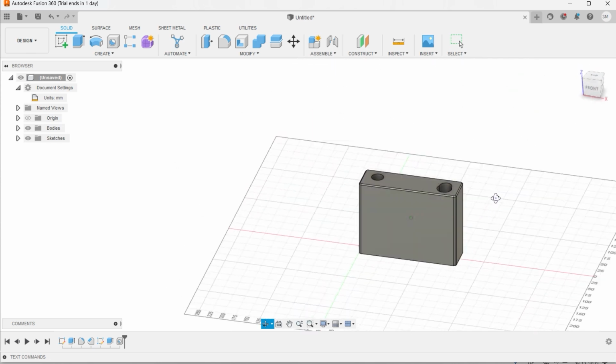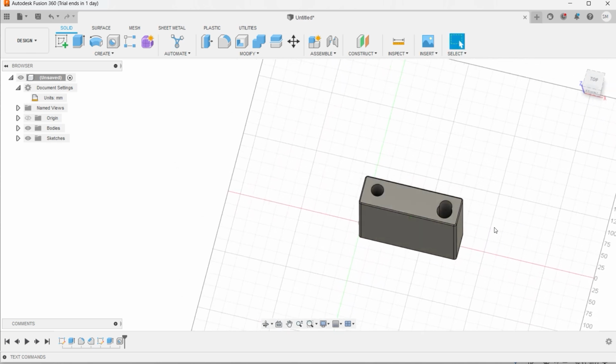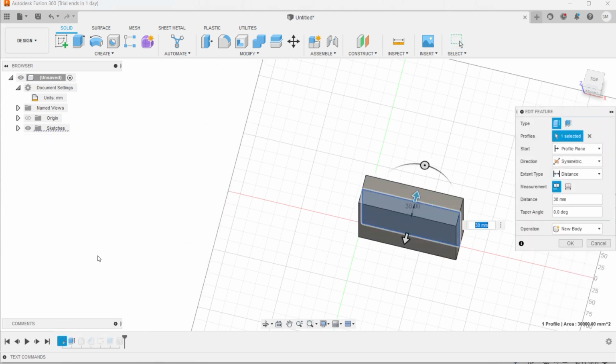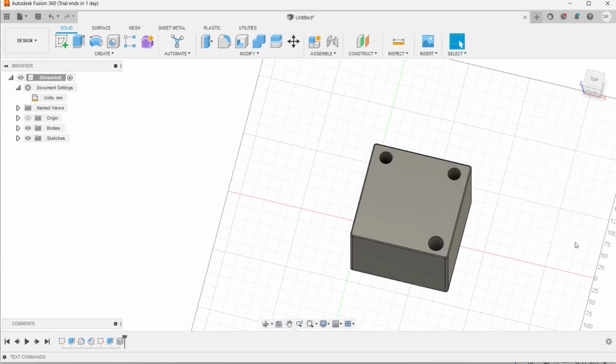this is up to you only, right? If you want to make it more, it can be done again. So let us edit features, and when we extrude this one more, let the extrusion depth be 100 millimeter. Okay, done.